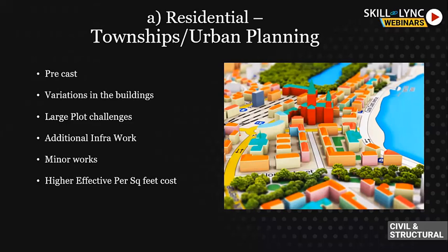Another challenge is that since these are horizontal developments, the plots are very huge. The surveys are quite extensive. And if you look at the geotechnical investigation of these plots, you might see variation in the soil profile and the rock profile underneath. Every building might look the same but have a slightly different substructure below ground. It might just happen that rock is encountered at, let's say, 2 meters at one building and 8 meters at another building, so you will probably have to design the buildings for different support conditions also.